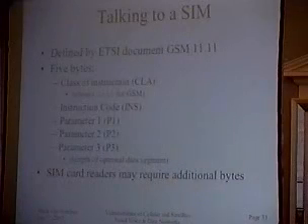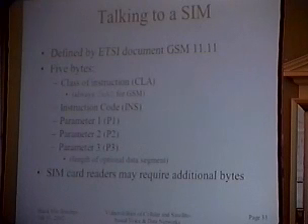For a GSM SIM, there's a specification that fully spells out all the things the SIM is supposed to do. It lists the instructions that the SIM is supposed to follow. When you talk to the SIM, there's a class that you have to provide, and for GSM it's always A0. The actual instruction that you want the SIM to execute, and then the parameters for it. It's interesting to probe SIMs for undocumented instruction codes. There are almost always codes that the manufacturer uses to test them, either in design or in production. So there are codes that are not documented but sometimes do interesting things.